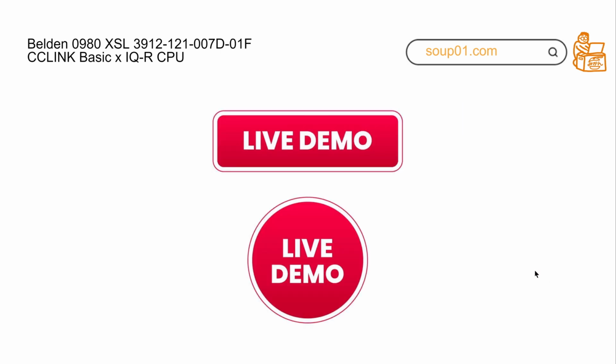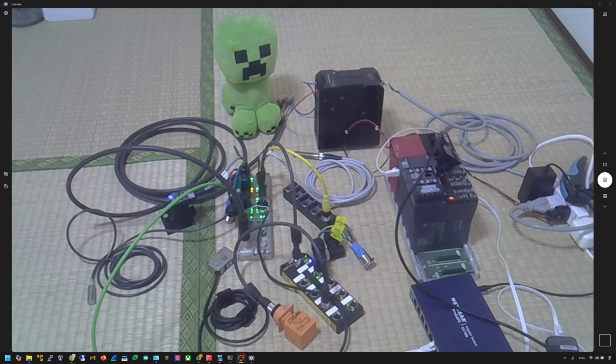Okay, I think the basic introduction is enough. Now I will turn on the camera to show you the hardware I'm using this time. Here is the camera that I turned on. You can see on the right-hand side this Mitsubishi CPU is iQ-R, and the LAN cable is connected from the integrated network port to the network switch, and the Belden module is connected to the same network. The other three modules I'm not using this time, so please just ignore them.